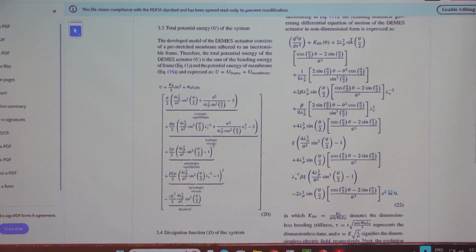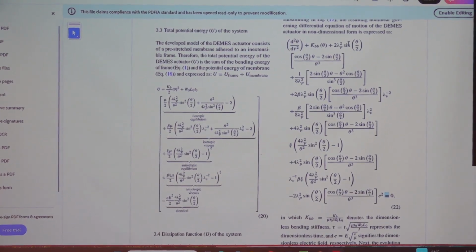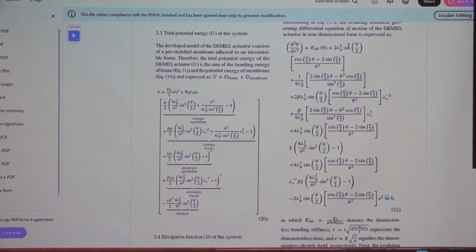So it is going to vary the case. If you put the anisotropy parameter to be 0, what will it become? The membrane will become isotropic when the anisotropy parameter is 0. When you consider the anisotropy parameter, it will be aniso-visco-hyperelastic. When you consider the viscous component to be vanished, it will be an anisotropic membrane only. So you can play with the parameters, and you develop a generalized model. Now if you say I want to solve for the isotropic case, the anisotropic part will vanish.